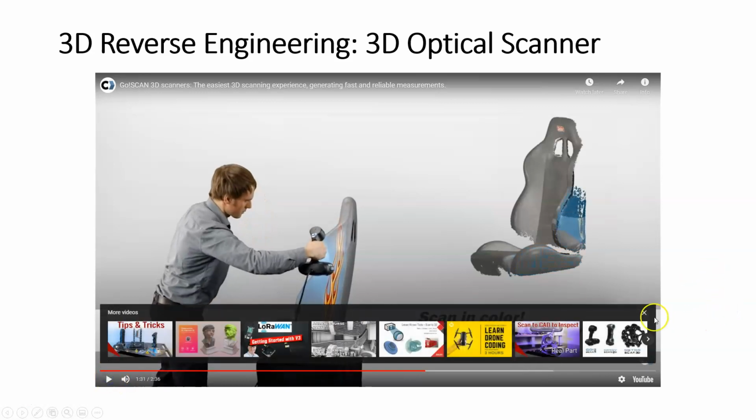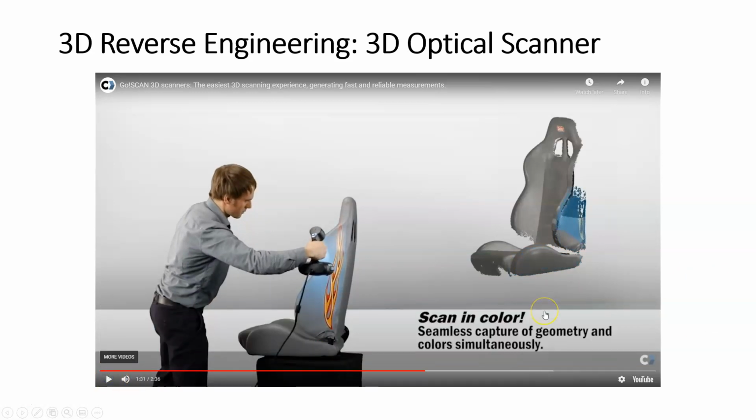Okay, very simple, very quick, but realize that this does take some checking. The STL file, or excuse me, the 3D CAD model that you're creating here is not always a perfect file, and many times you'll have to go in there, inspect it, repair it, make some changes to it. So, even though this is quick, it's not necessarily foolproof.